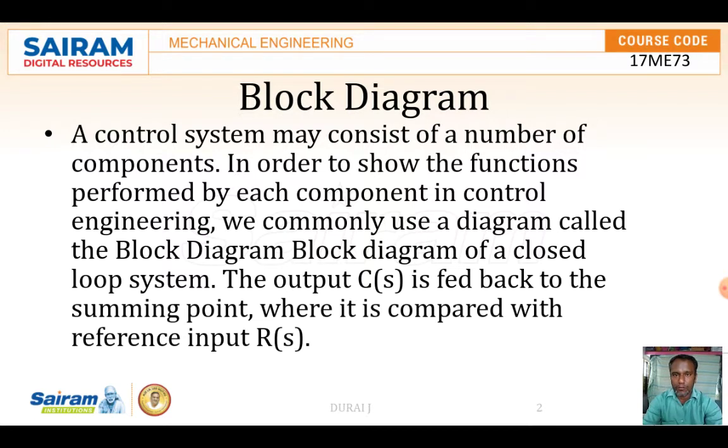Also, in this type of block diagram problem they are going to provide many blocks that we are going to reduce into a single block. Once we give the input, we get the output value. If there are so many blocks and we go and find the transfer function of all the blocks, it will be time consuming. So we are going to reduce the blocks over here.